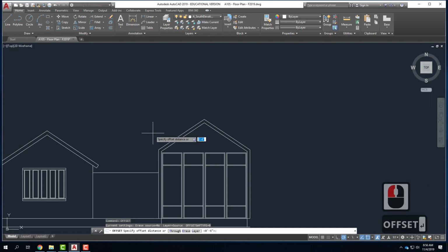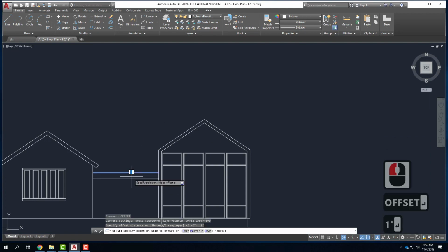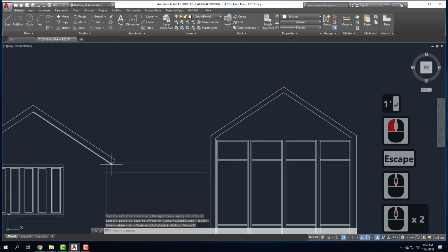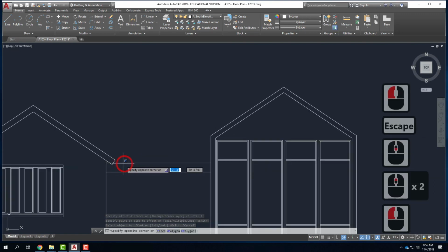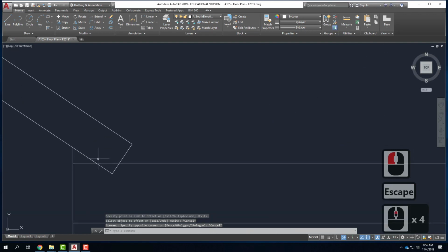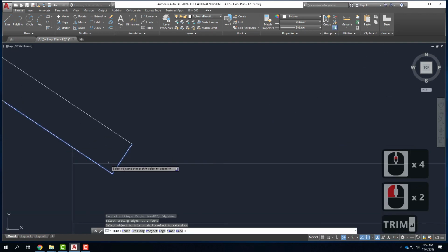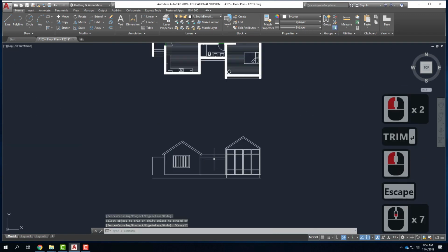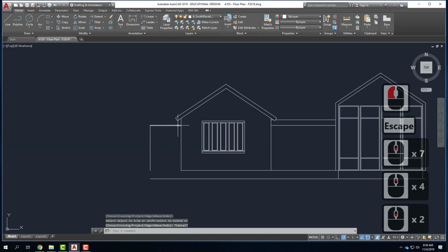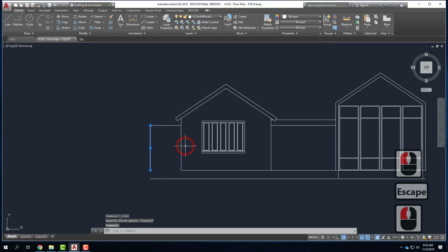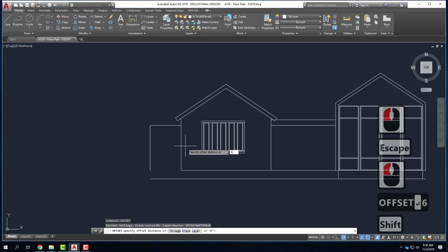So let's take this. I'm going to offset this by 1 foot, like that. That'll be the roof for this particular section. Boy, this is turning out to be a really ugly building, but such is life. And I'll trim that part off because it's behind. Likewise, I have this little entry alcove here with some stairs. So on this edge, I've got a little 6-inch wall, so let me offset that by 6 inches.